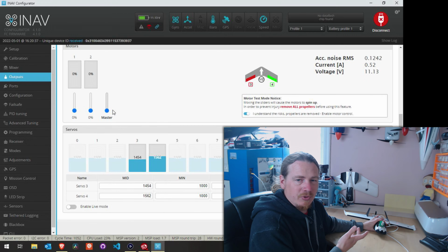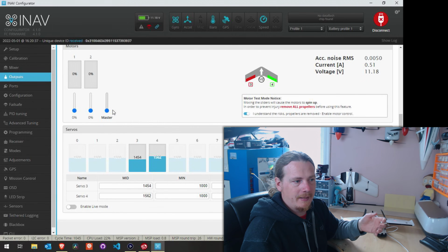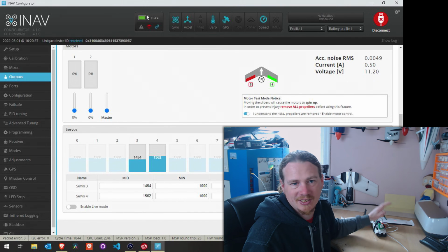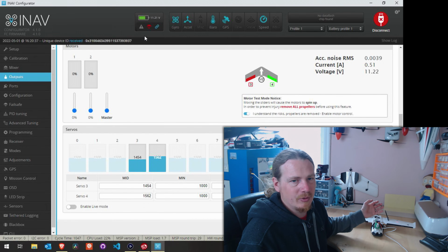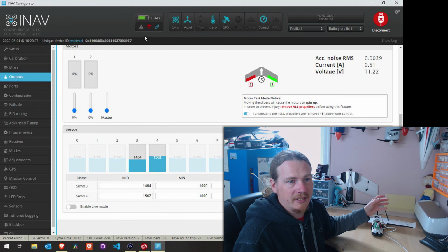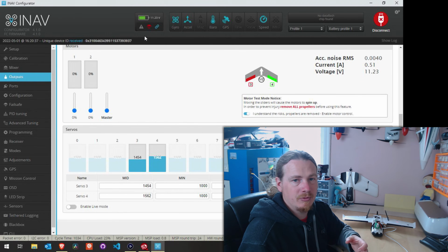So yeah, you just want to feel it so all the weight of the plane is taken, and of course try and do this with a fresh battery. This battery is at basically its storage, so that's probably why it felt a little bit weak at that 90%, but it should feel like it's just trying to lift off. You've got basically slightly more than the 1-to-1 power to weight ratio.